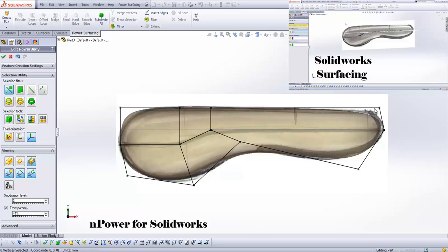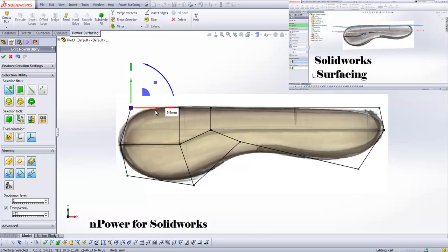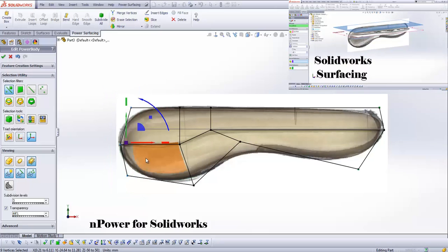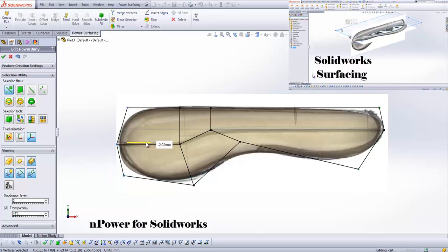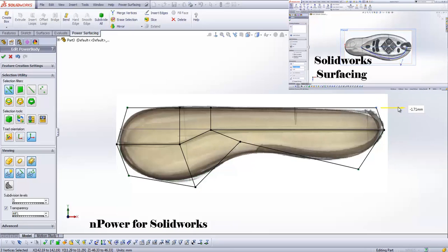So you can see here I'm just flattening things out by using that scale command. We've got translate in all directions, and we've also got scales in multiple directions. You've seen me using these little arrows, as well as that little fan, which will allow me to move in plane, essentially. So I can move things in both directions at once rather than specifically using arrows. I'll use a combination of those two tools as I'm working through the process.